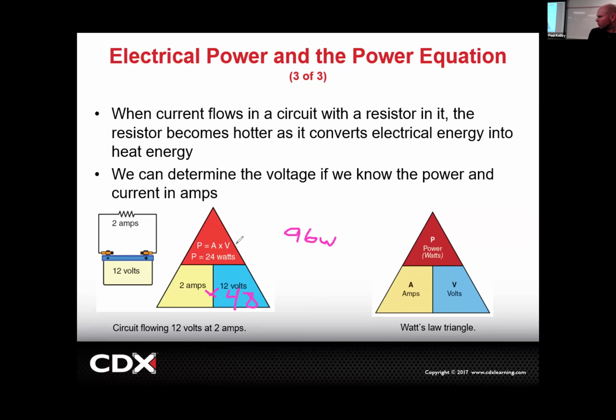If you want to increase the volts, that electrical pressure is going to be hard to contain because it tries to push out, right? There's a lot more pressure, so you can't have your basic insulation. You've got to have thicker insulation. Like, for example, on hybrids and EVs, you know they have the orange cables. That means don't mess with that because that's high voltage. So 12 volts is no real harm to you, but a lot of hybrids and EVs are running 200-something, some are on 400 volt. There are even some running 800 volt, but they mostly keep that isolated in the battery.